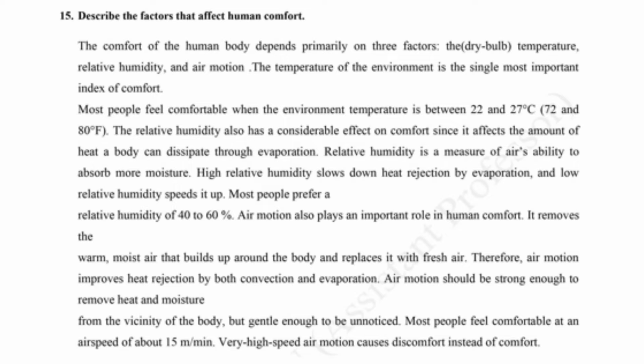The temperature of the environment is the single most important index of comfort. Most people feel comfortable when the environment temperature is between 22 and 27 degrees Celsius. Let's say 72 and 80 Fahrenheit.